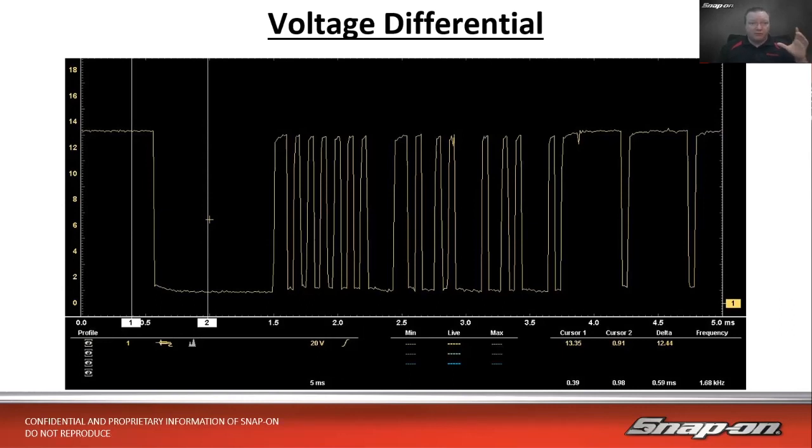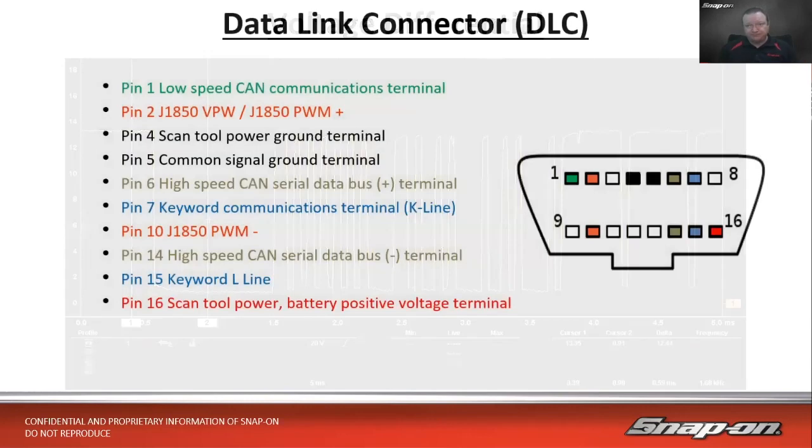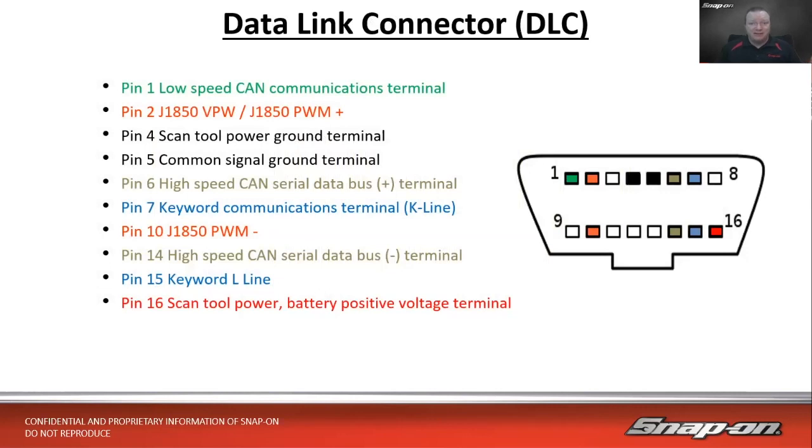Around about 12 volts, give or take about half a volt or so, is a good signaling range for that. Anywhere outside of that, too high or too low, the computer might consider it invalid data and decide not to use it. All right, so we want to make sure, depending on our network, what voltages we're looking at. And then how are we going to test the networks?